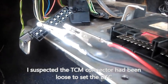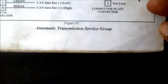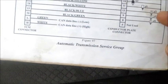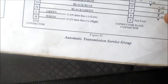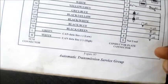I'm just going to double check the 3 other solenoids. According to the repair manual, there are 3 other solenoids here. This is the repair manual. The solenoid we are talking about is this one. But there are 2 other similar ones, Y4 and Y5. So I'm going to double check that their resistance is also correct.